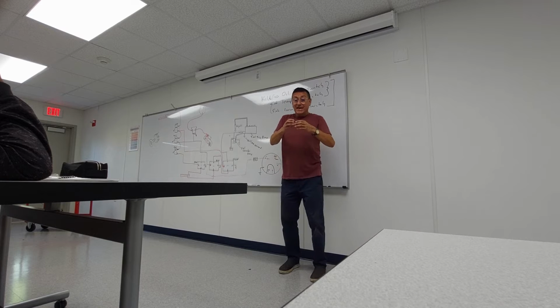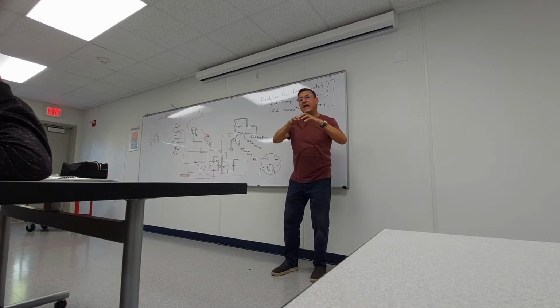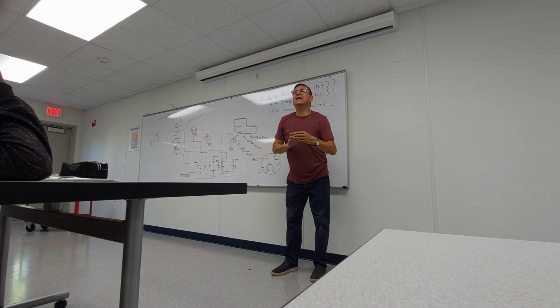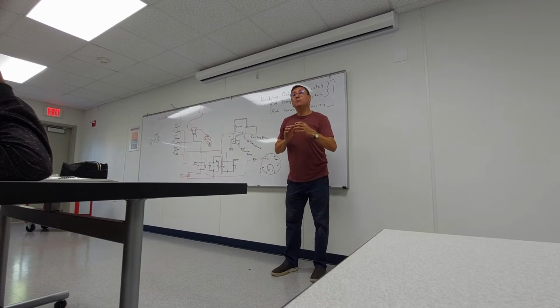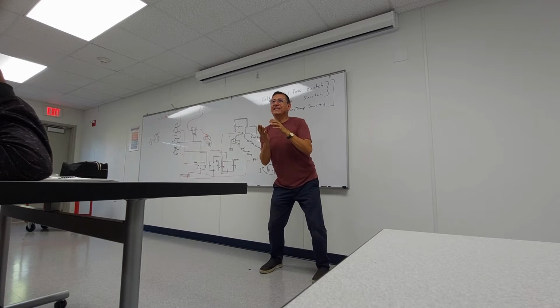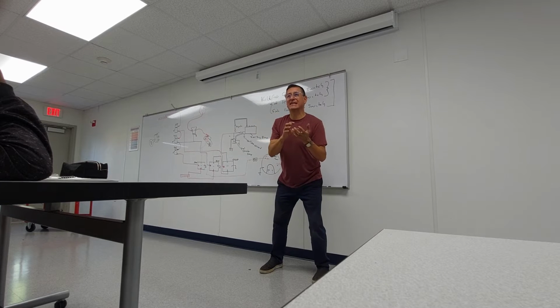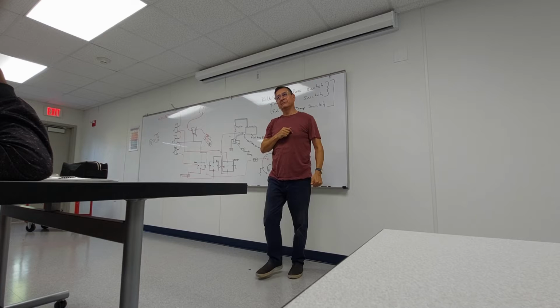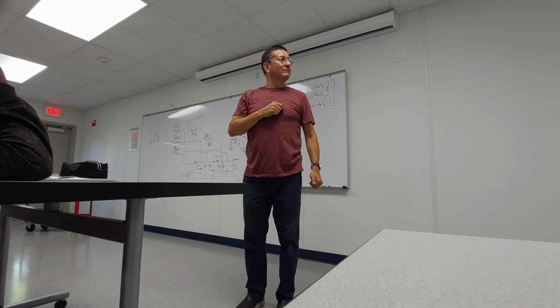The metallic element where the thermostat is located is called the thermostat housing. The sensor and the switch are located at that point because it is the breaking point where the temperature of the coolant changes dramatically. For that reason, those sensors are located there. If you watch the gauge, you can actually see it physically.